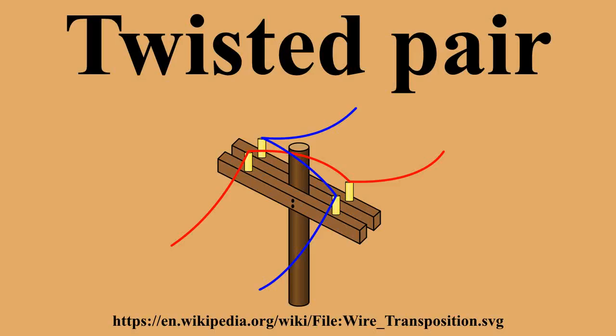Common types: solid core cable versus stranded cable. A solid core cable uses one solid wire per conductor, and in a 4-pair cable there would be a total of 8 solid wires. Stranded conductor uses multiple wires wrapped around each other in each conductor, and in a 4-pair cable with 7 strands per conductor, there would be a total of 56 wires. Solid core cable is intended for permanently installed runs. It is less flexible than stranded cable and is more prone to failure if repeatedly flexed. Stranded cable is used for fly leads at patch panels and for connections from wall ports to end devices, as it resists cracking of the conductors.